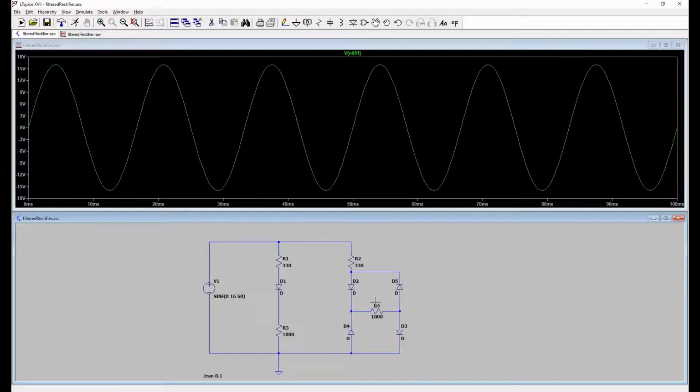With the full wave rectifier, as you recall, we had to move the black clip on the oscilloscope probe off of the power supply and onto the resistor itself due to the diodes that are changing the characteristics of the reading at the output. But we're not going to do that just yet. So the input from the AC supply is of course the same for both rectifiers.